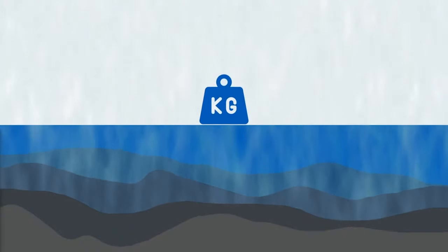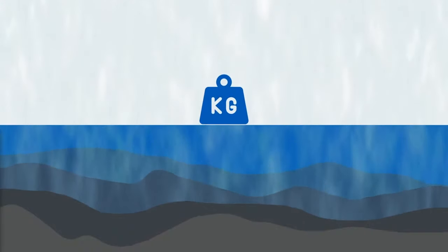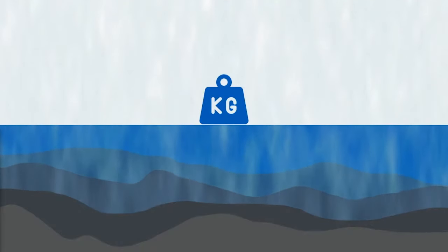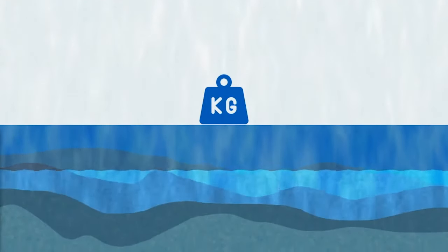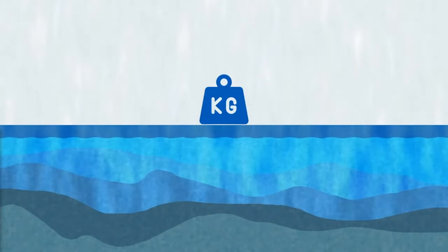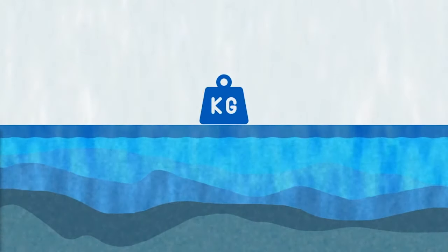As well as determining the load-bearing capacity of the soil and rock on a site, care also has to be taken that the eventual structure is kept free of damp and water ingress from the soil, so an understanding of the water table on site is also important.